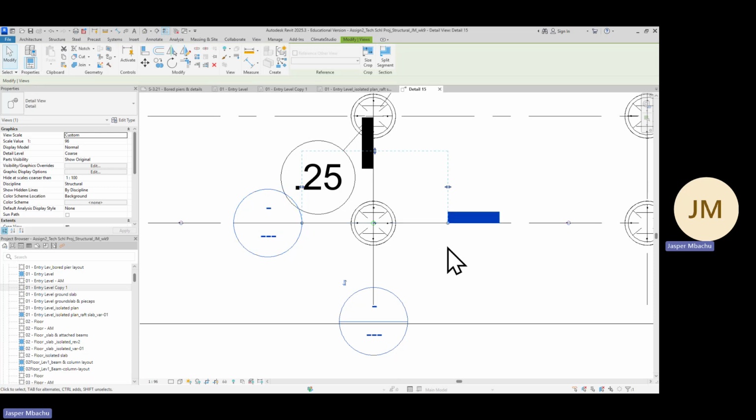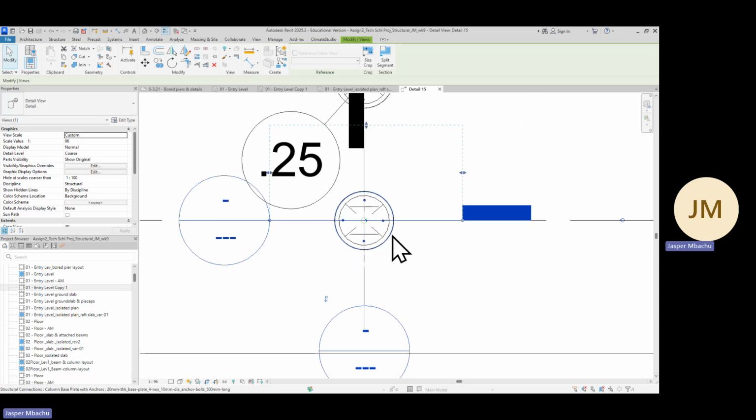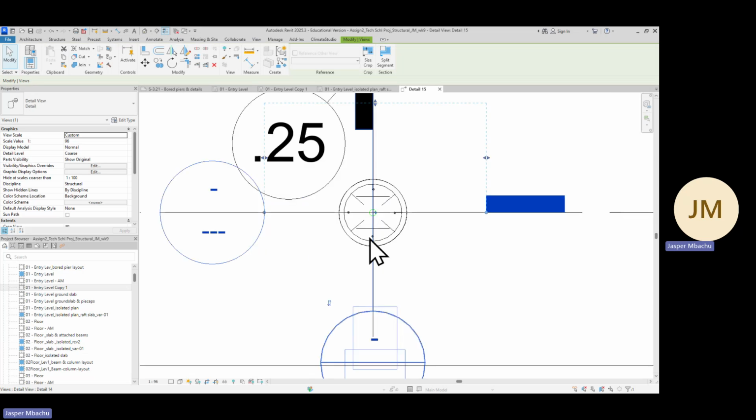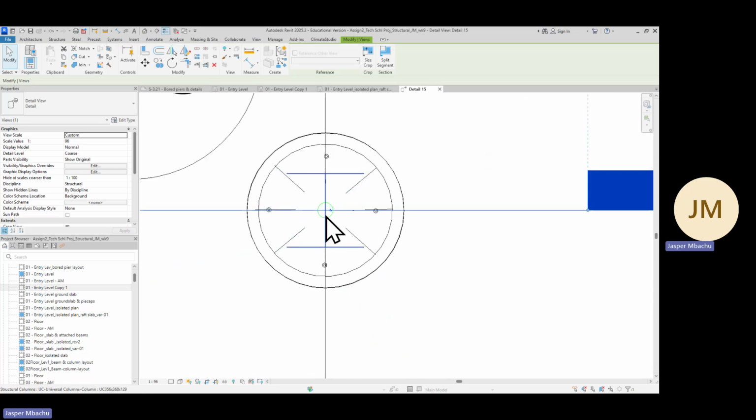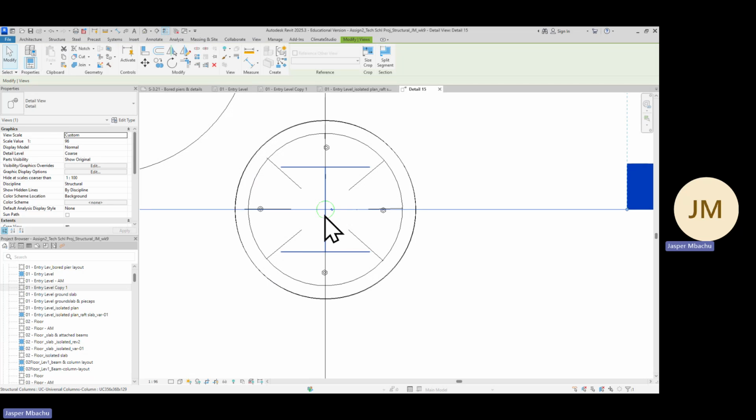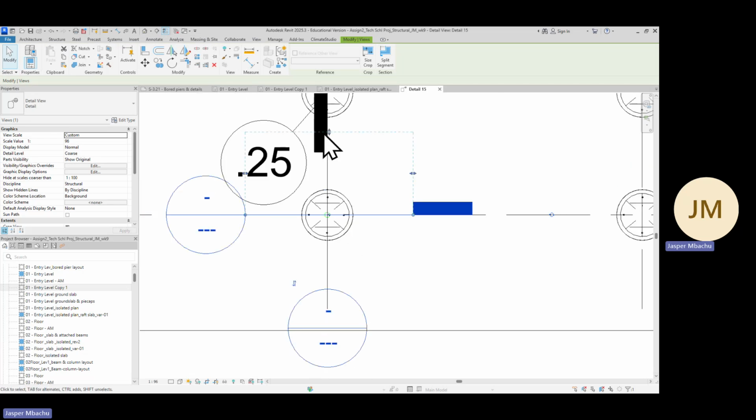If not, it's going to get skewed. So provide a section line there, and also vertically. Make sure that that section line is aligned with the grid line, because that is going to make it cross to the center line. So also put a vertical section line.